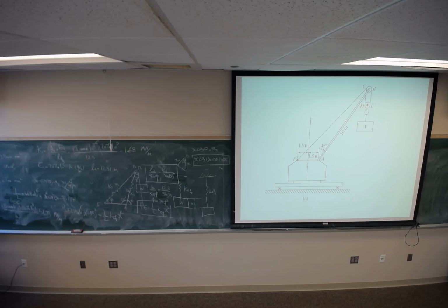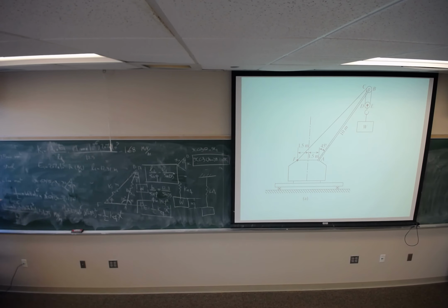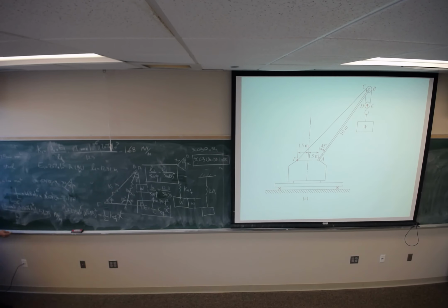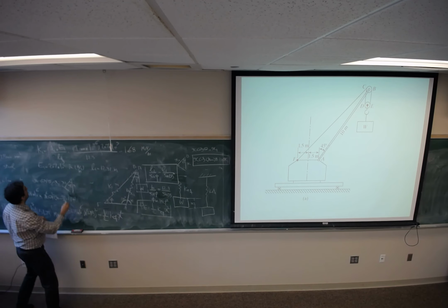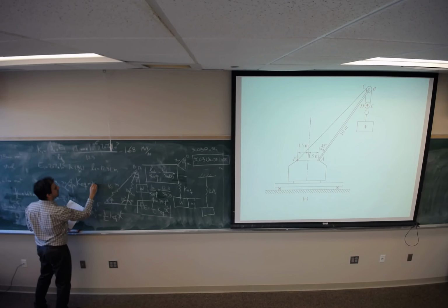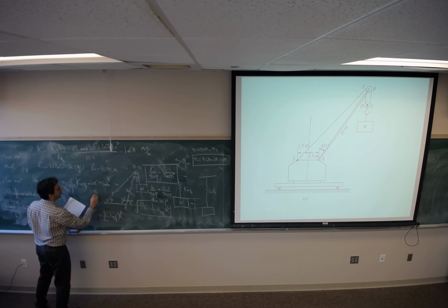In almost all of the problems that you are solving with the energy method, you should cancel out the variables that you have. Then you can solve for k equivalent. If you cancel out this half, then k equivalent would be this plus this, which is 26.43 times 10 power 6 Newton per meter.